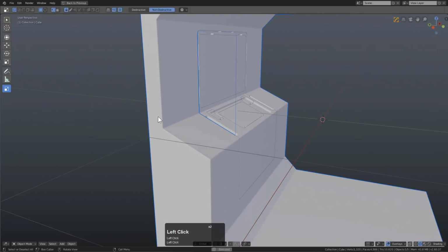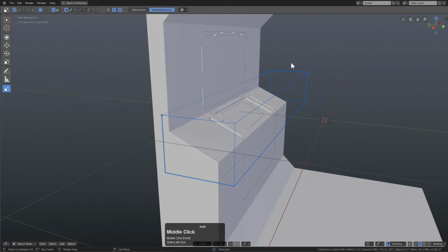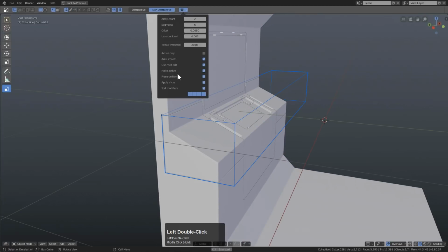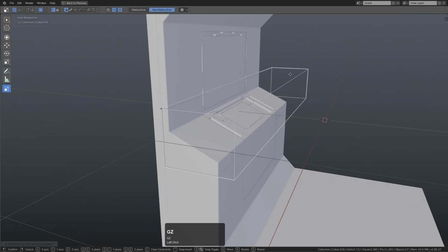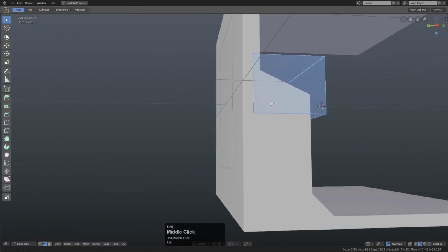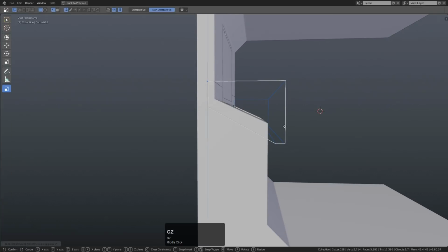So right here, I'm just going to draw a box all the way across, turn it to a slice box. I'm going to hold shift, click and apply. Now normally with apply slices, it would apply to slices, but we had it where shift serves as an override, part of that behavior update. So now we can go in and just modify this mesh, and it will actually update our slice.